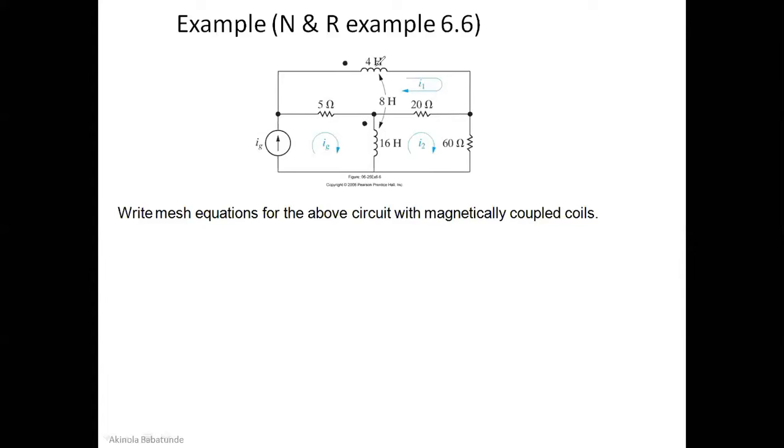You can see we have a coil. You can label this one coil, and this the second coil here. We have a current source here, a resistor here, another resistor here, and then there'll be mutual inductance here. All right. So the first thing you want to do is define your polarities before you start anything. Otherwise, you might get it messed up along the line.